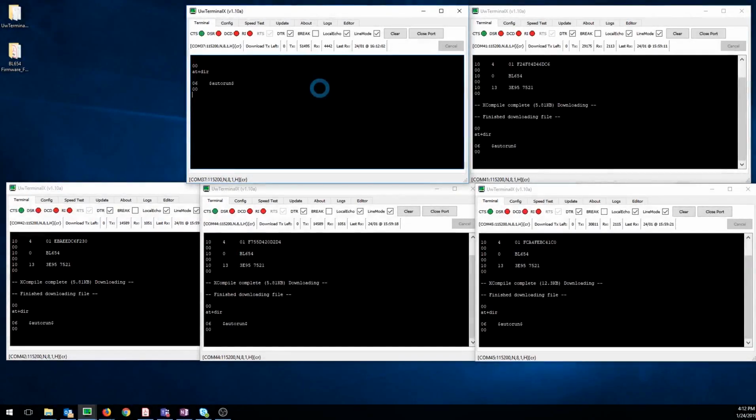If necessary, revert the boards into an unprovisioned clean state. If this is the first time you are running this test, and the boards are already in a clean and unprovisioned state, you can skip this step. But if at any time you think the boards may have non-volatile mesh information, or you are uncertain, it's best practice to revert all the boards. So if you clean one, clean them all.